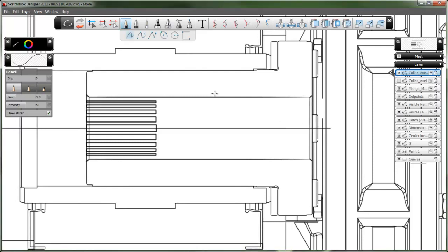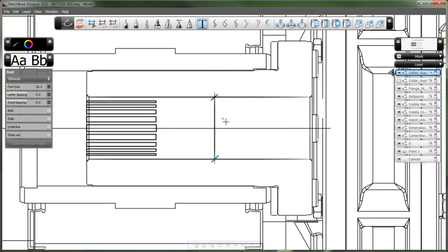Notice that we quickly set up a mirror plane and begin sketching out the proposed change. The spline is quickly sketched and mirrored with most of the other geometry turned off, all in 2D. Then, a simple node is added to define exactly the type of spline shaft needed, which will be another pre-purchased part.